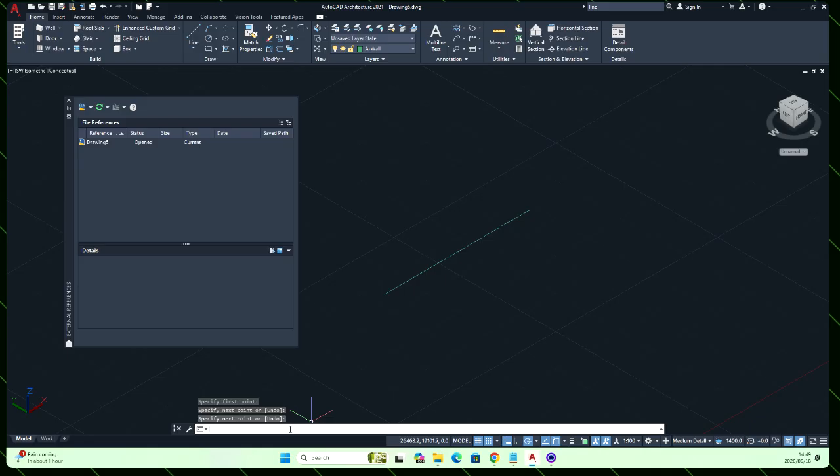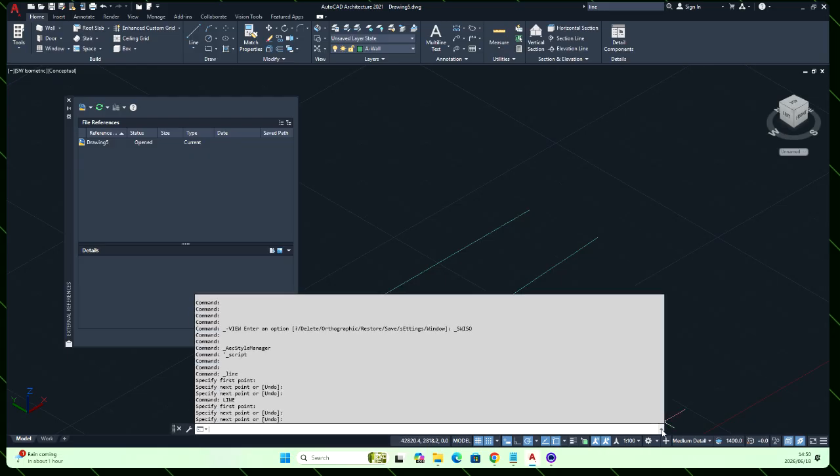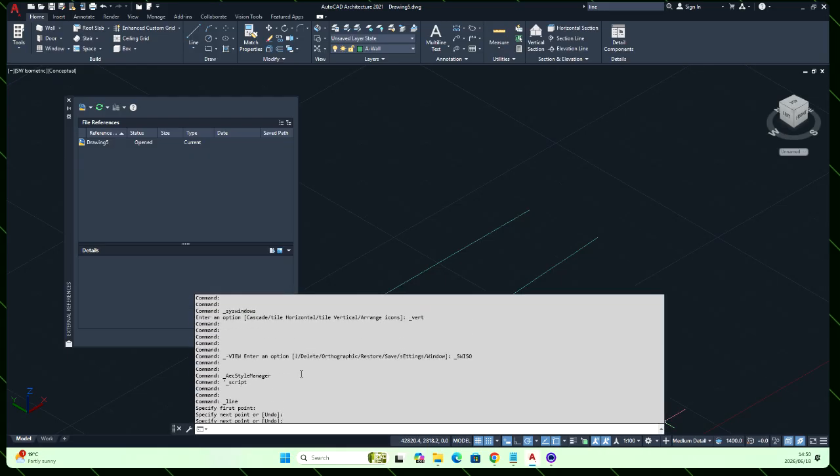But now the same thing in the command bar, you can just type line and it'll give you a list of options. You'll get used to this. And just enter, same thing. Sorry, space to enter. Now, each action that you do does have a different flow of the commands or tasks that you need to do. So just be mindful of that. And if you don't know, just read the command clearly. You can open up this and you can see exactly what was done.